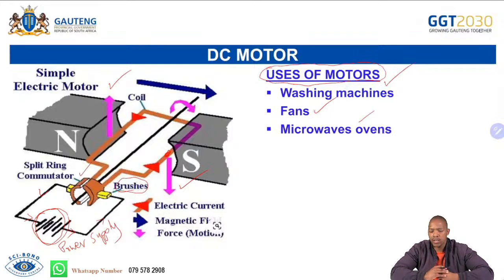Right. Design then. For the generators, you have 2 types, an AC generator and a DC generator. For an AC generator, we're expecting to see a load, a coil, carbon brushes, but most importantly for an AC, we are expecting to see slip rings. We must see slip rings. That's an AC generator. For a DC generator, there must be a load again, there must be a coil, there must be carbon brushes. However, to differentiate from the AC, we must see split rings or a commutator.